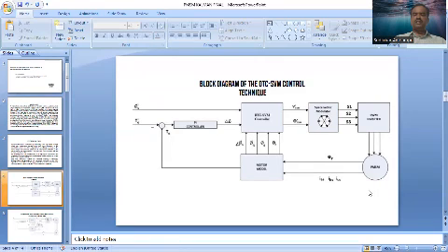The different stator currents IAS, IBS, ICS are sampled, and the rotor position theta is also sampled continuously and given to the motor model as input. This motor model will be providing the stator flux, the stator position, then DQ components of the flux and rotor position as input to the DTC space vector modulation controller.